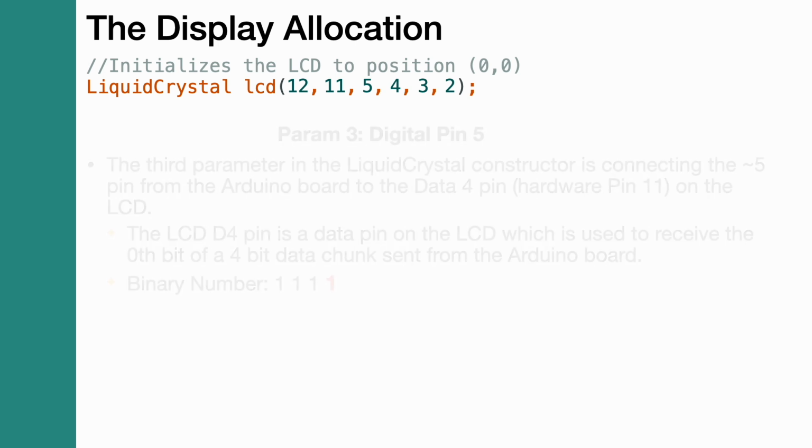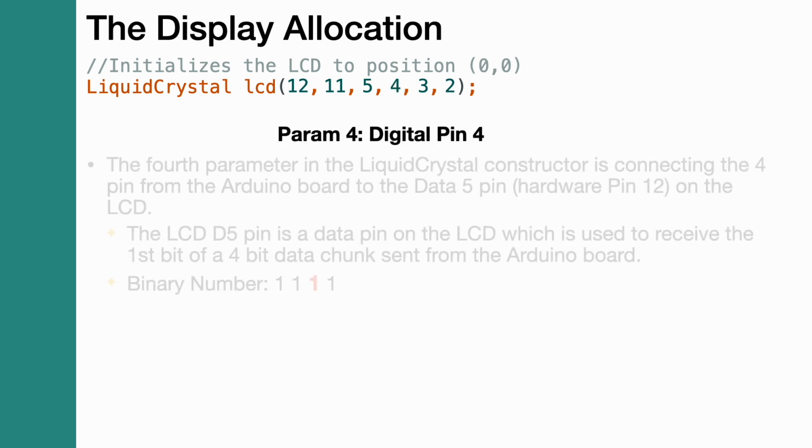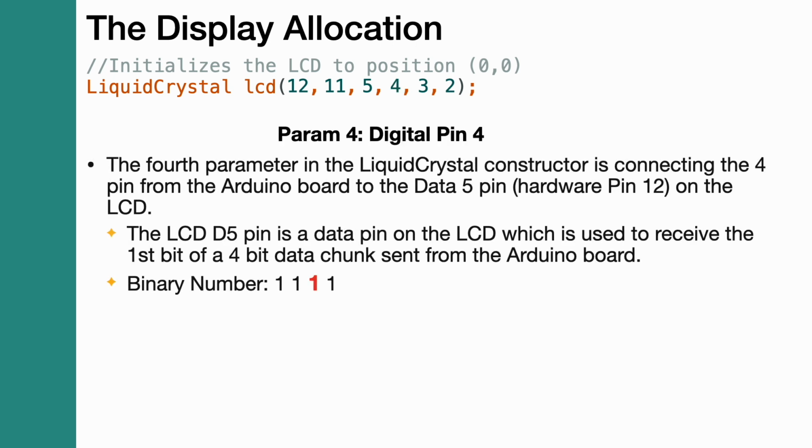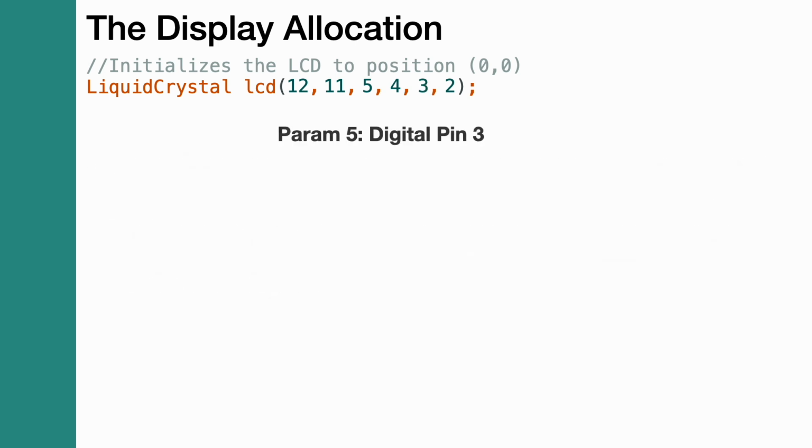They're just going to take in different digits of the binary value, and they're just going to go into different pins. In this case, our Arduino digital pin 4 is going to go into pin 12 of our LCD, and it's going to read in this first position bit. Again, we have the 0th, 1st, 2nd, 3rd. And that 3rd position, in this case, we also call the most significant bit. And again, 3 here, no different.